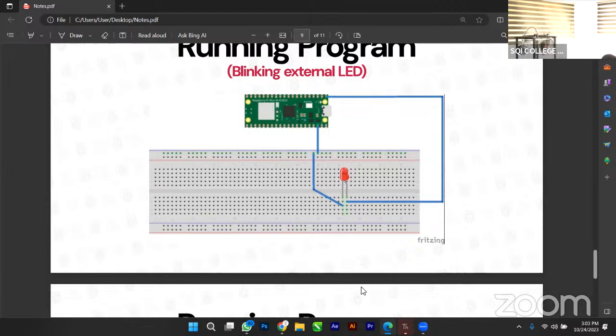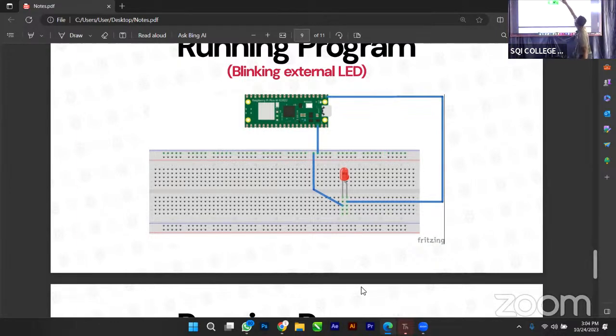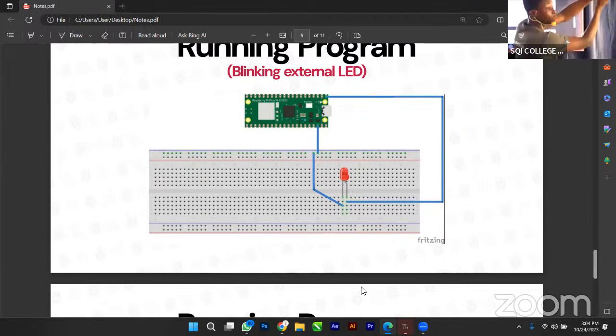Now, look up everybody. I go again. This is GPIO 0 on your Pico. If I connect my GPIO 0 with a wire to any rail on this point, it means that the positive is connected to that pin. Remember what I said? Every port on this column is connected together, from here to here.